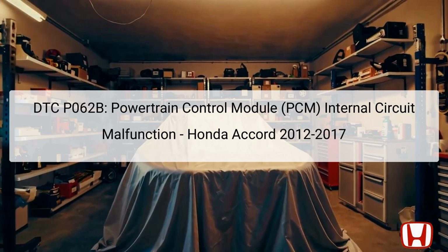The DTC P062B is a diagnostic trouble code indicating a malfunction within the Powertrain Control Module, PCM, internal circuit. This error typically arises when the PCM detects an anomaly in its internal communication, leading to improper functioning of its components. The PCM is essentially the brain of the vehicle's engine management system, controlling critical functions such as fuel injection and engine timing. In the Honda Accord from 2012 to 2017, the PCM's integrity is vital for robust engine performance.